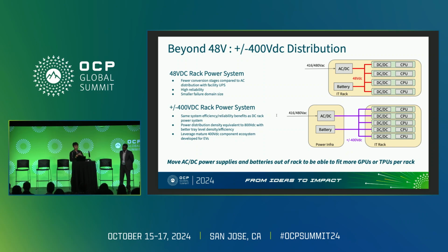That's to facilitate the transition to the plus minus 400 volts. Basically, we have very similar AC-DC conversion, and then we put the UPS function at the output of the DC, right? The only difference is that we aggregate all those AC-DC conversion and the BBU function into one rack or into one building level conversion system. But we can have similar interactions between rectifiers and batteries. So by doing that, I think we can optimize the performance for both the power design at the same time, also to give the most flexibility to unleash the power of the ML platform.